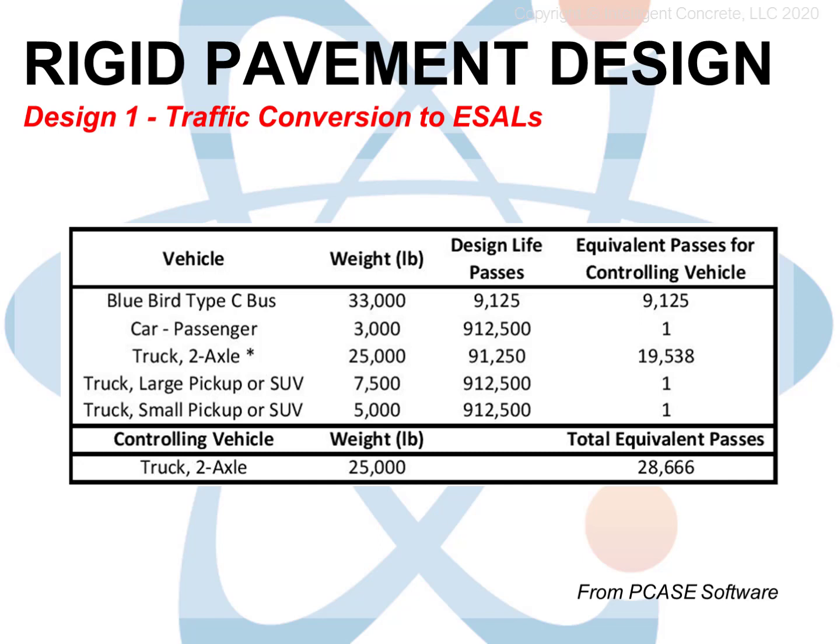The minimum pavement thickness for each vehicle and number of passes is calculated based on the traffic graphs in the following slides. The traffic graphs are dependent on the vehicle weight, and there's probably one that's been developed for the exact vehicle of concern or very close. There are dozens and dozens of traffic graphs in the UFC manual for different vehicles, and if you cannot find your specific vehicle, it is recommended to find the graph reflecting the weight and axle configuration closest to yours. Based on the traffic graphs, the vehicle with the maximum required thickness becomes the controlling vehicle.